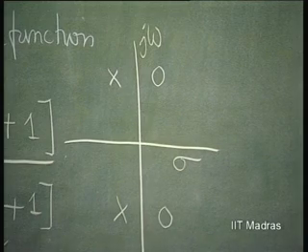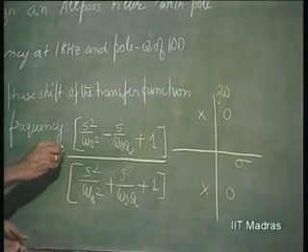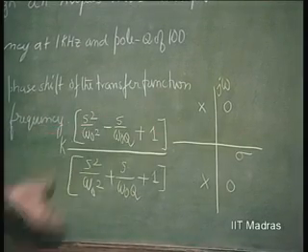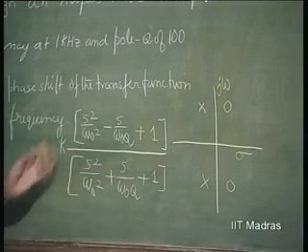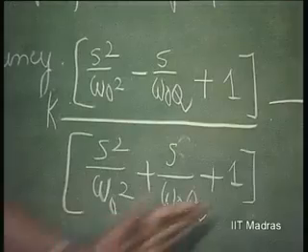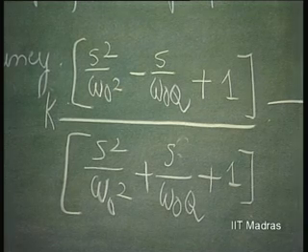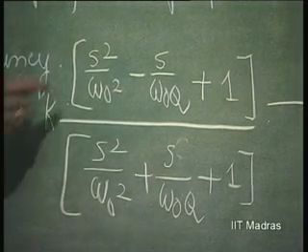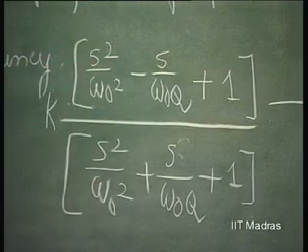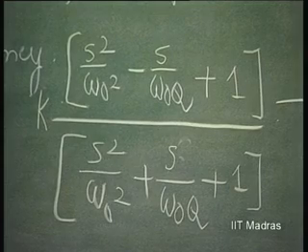Here, if you take the magnitude, magnitude is unity throughout, or if there is a k factor here, it is going to be k throughout for all frequencies, because if you take the magnitude, this will give you a contribution of unity, because only change of sign occurs, right. Whereas, the phase shift is going to be offered by both poles as well as zeros. So, contribution to the phase shift is going to be there, and therefore, this is going to be very useful